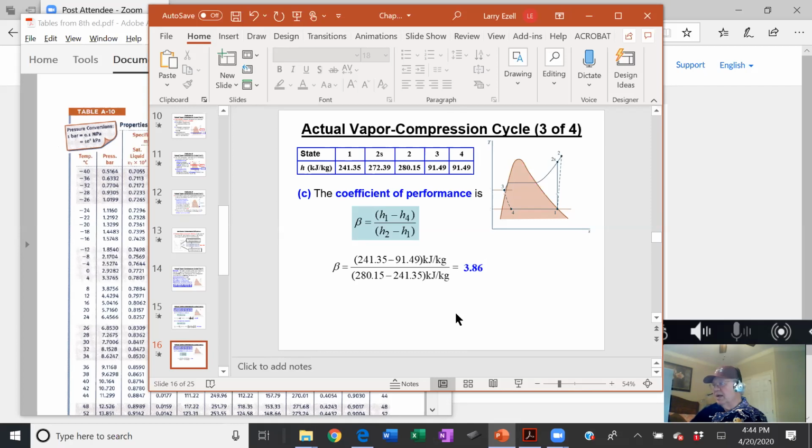And as it turns out, there's a conversion factor. I believe it's like 3.413 BTU per hour per watt, something like that. But it's easy to figure. And that would end up being about a 13 or so SEER, which is pretty good.